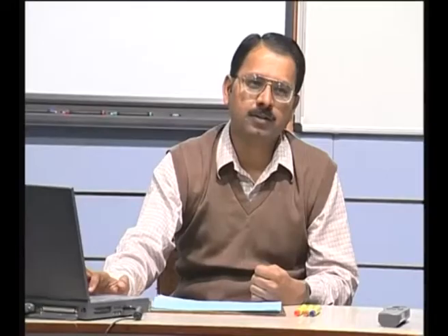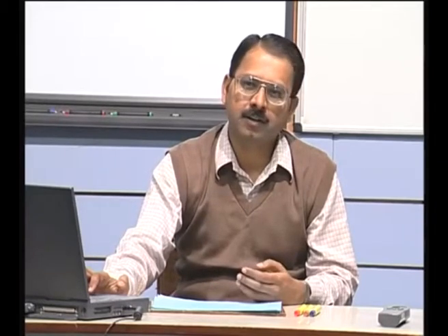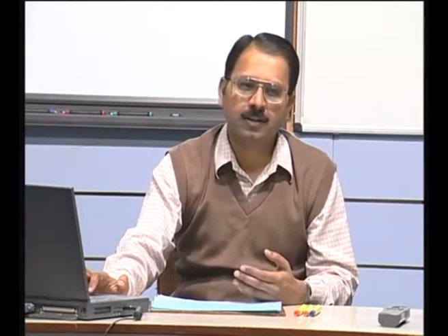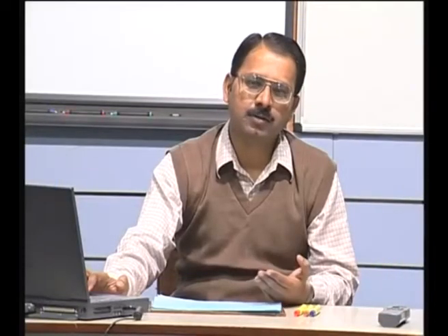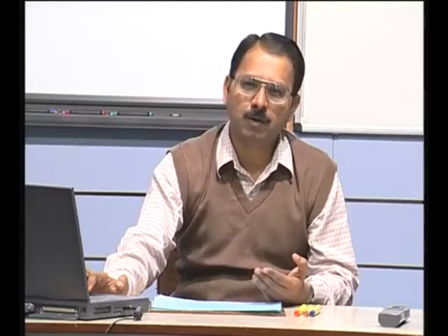For example, you may have heard of stereolithography, selective laser sintering, laminated object manufacturing, or fused deposition modeling. These are all examples of rapid prototyping machines which build an object slice by slice, and they usually use raw materials which are either polymeric monomers, or polymer or metallic powders to carry out this particular sintering process.